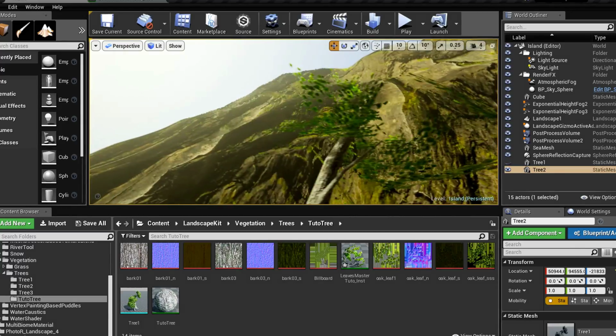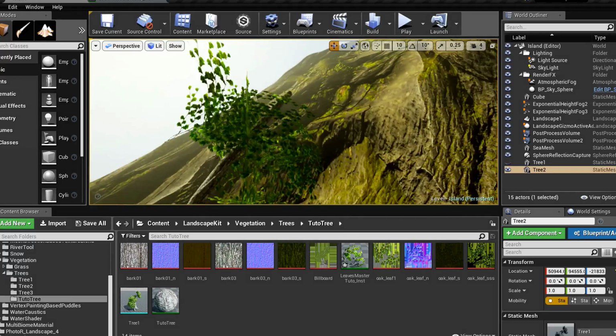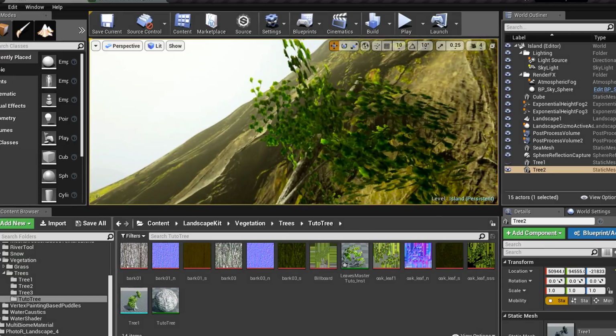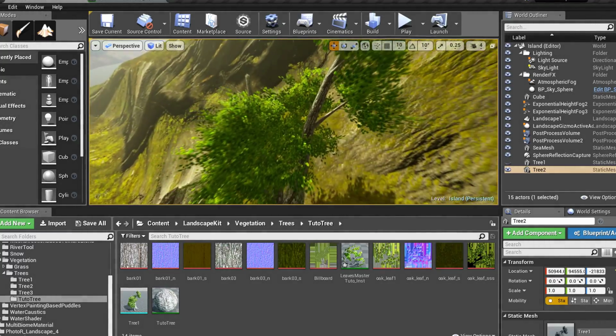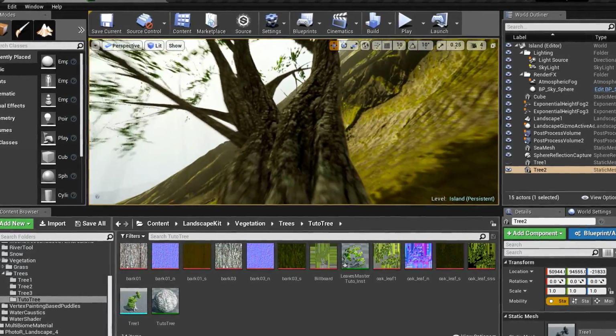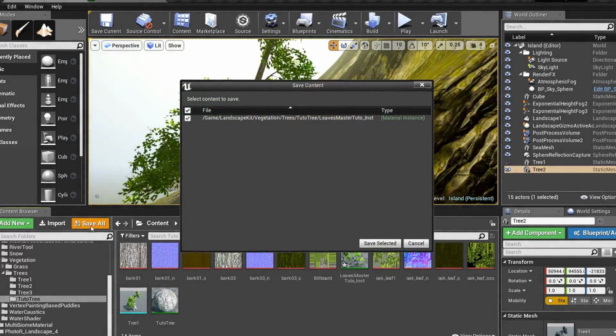So what you want to do is rotate the UVs of the mesh, so instead of reading the textures like this, it reads the textures in the proper way, so that this stem part, this small twig-like part, the end of the leaf, the start of the leaves, is near the branch, and that is something we desperately need. I'm going to show you guys how to fix it in part 3. So hang on. Goodbye until next time.